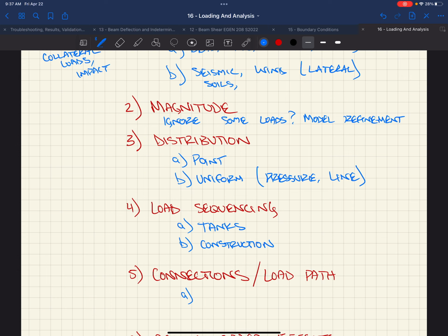And so we had to think about when they are going to pour concrete on all the subsequent decks, right? I mentioned that there was a problem. I can't remember what building it was, but we cambered the beams and we over-cambered them to try to make up for the dead load deflection, but we assumed that there was going to be more weight on it than there really was, based on the construction sequence that they were choosing, right? We assumed that all the dead load from all the diaphragms up above, they had poured all the diaphragms. We just used the dead load like in the homework, 60 pounds per square foot. We said that that was there on that column sitting on that girder, okay? When it really wasn't when they went to pour the floor. So then all these studs are sticking out of the concrete, right? Not good, right? Not good.